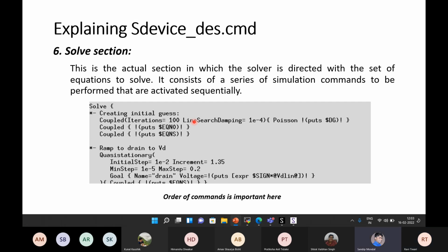Okay, sir. Kunal, to answer your question, what is the minimum length you can take? The minimum length is your atomic length, right? So you can build one atomic transistor, and you cannot go beyond that, lesser than that. So if you are going for a 20 nanometer channel length and you want a good and accurate solution, you can have 40 points, like half a nanometer each. That would be a good estimation or good understanding of what you are getting.